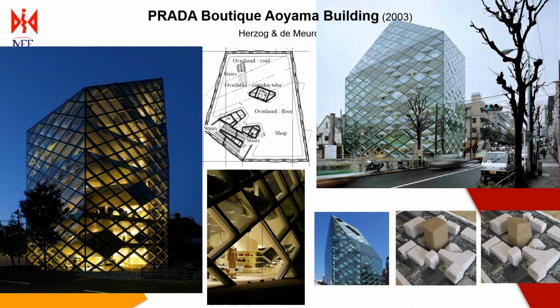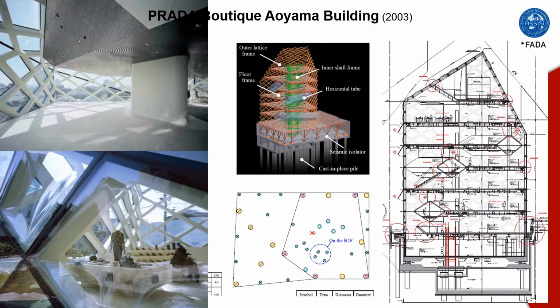Base isolation system is under the basement. Therefore, a perimeter space was necessary for the free movement of the building. The horizontal loads were reduced in the structure, allowing thus the use of rhomboidal grid made up with big glass sheets.